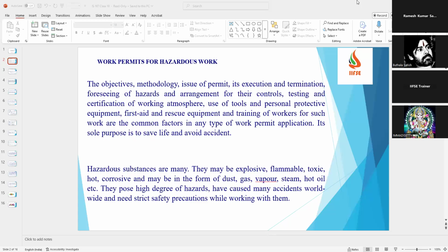It does not mean only the safety officer reviews the conditions; the area owner also reviews the conditions of the workplace, whether it is acceptable, all the hazards have been identified, and all the respective safety precautions have been implemented or not. They will cross check. As a final check, the safety officer will visit the place, then sign on the permit. Once all the designated persons have signed on the permit, it is allowed to start an activity.